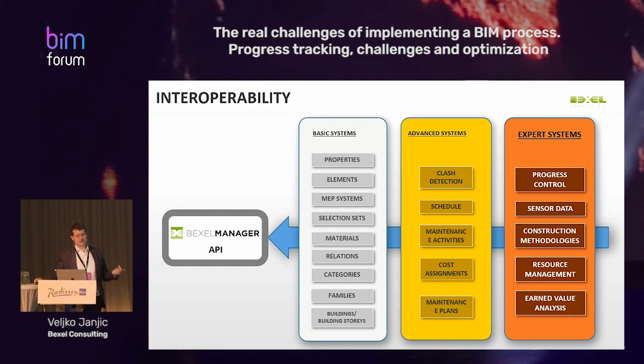Clash detection: you can combine clash detection and schedule. As I explained, I'd like to see the clashes which happen in the next 2 months, because I want to focus on them. Mileta will tell you about that project in Kuwait, where we had more than 100,000 clashes. If you don't organize them by priority, it's nice to have that information, but you don't have a clue how to start solving them.